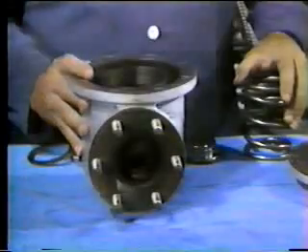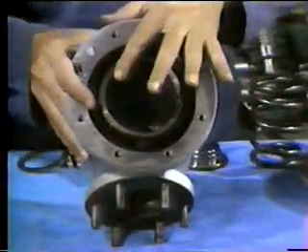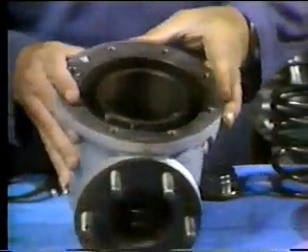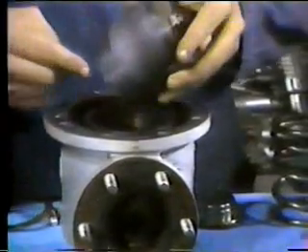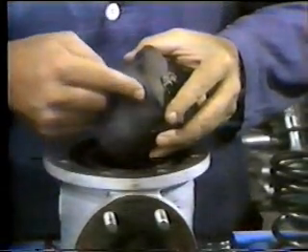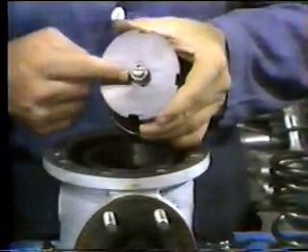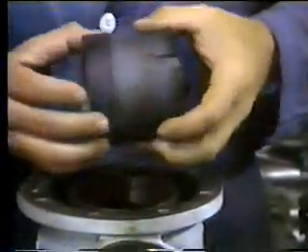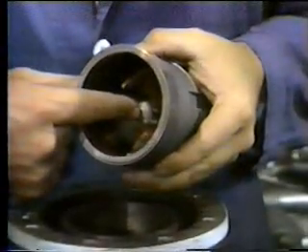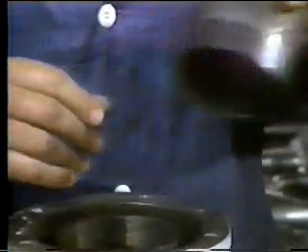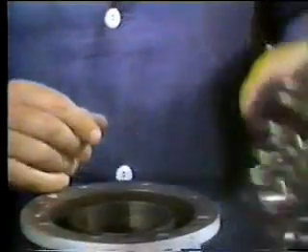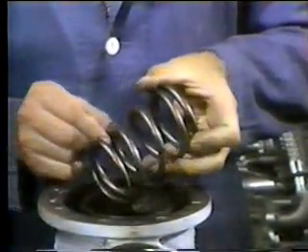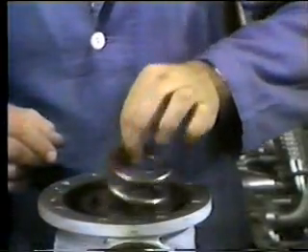Wash the parts thoroughly with Stoddard solvent. Do not use any abrasives. Inspect the components for damage, nicks, cracks, scoring, and evidence of binding or excessive wear. Inspect the adjustment screw for tightness. Inspect the end that contacts the spring seat for wear. Check the spring for wear in the thickness of the convolutions. If the valve has been damaged, replace it.